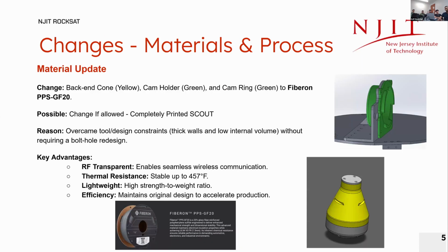So, some changes that we've made so far, specifically for Scout. I remember we were talking to you about this, Wesley, was the material chosen for Scout and for Overwatch. We're thinking of choosing a glass fiber infused PPS. There's multiple benefits for this. One, it makes Scout lightweight, it has good thermal resistance, and it's RF transparent. That is really crucial for us with the RockBlock sending signals over, and also with thermal resistance, it was a good choice.